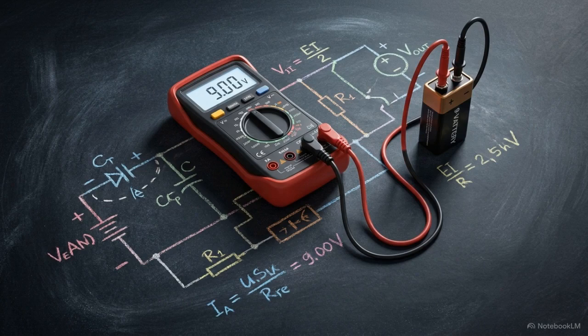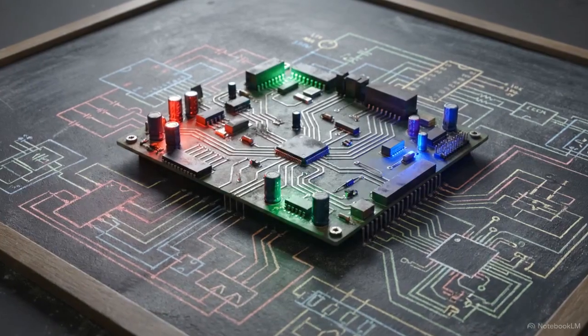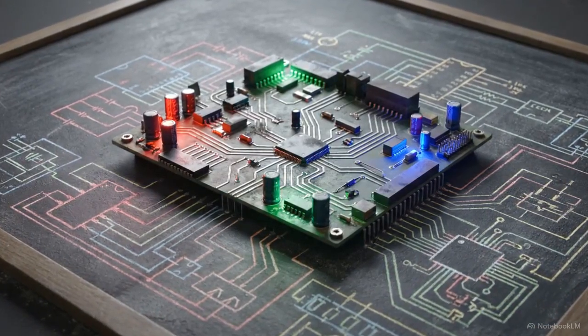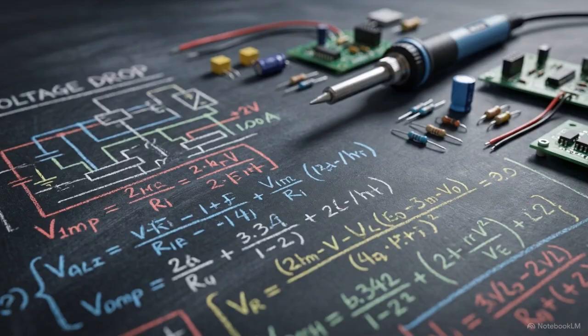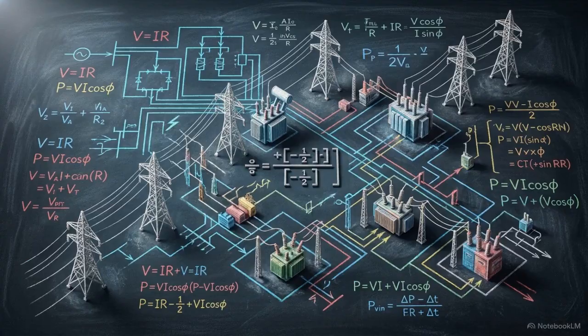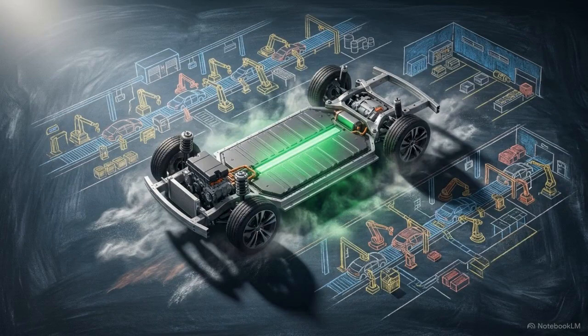This leads to a very specific diagnostic trap. A battery may show its full rated voltage on a high-impedance multimeter, yet drop below the required operating threshold the exact moment it is asked to drive a heavy physical load. You now possess the exact mathematical tool to predict and calculate that internal voltage drop before you ever solder a component. Mastering these algebraic models provides the foresight needed to account for internal constraints before they manifest as errors in practical engineering.